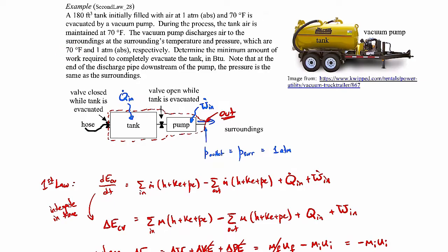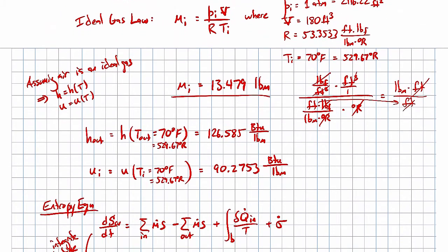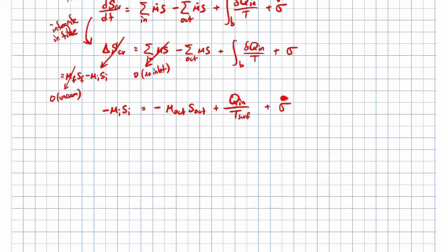And so that would be the temperature I would use, a little bit further out. If I did that, then you just have to keep in mind that this entropy production would include some entropy production in the surroundings. It would include the entropy production caused by the heat transfer through that thermal boundary layer. So this goes back to a previous example in a previous lecture, where you may have to include part of the surroundings if the surface temperature is not well defined. However, in this case, it is well defined, so it's not an issue.